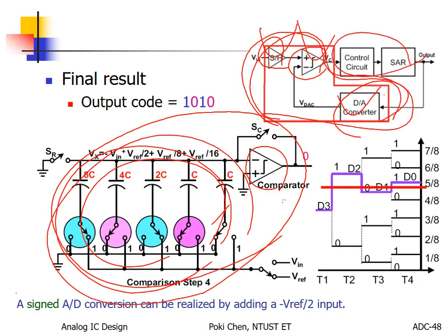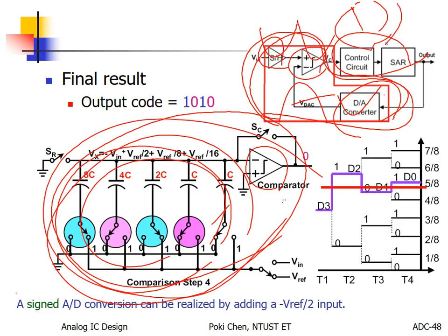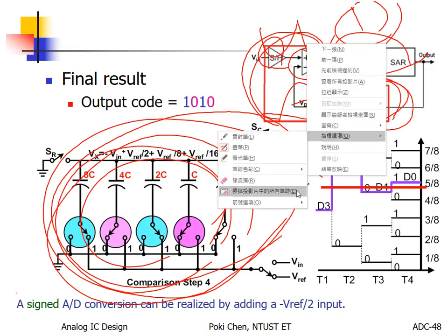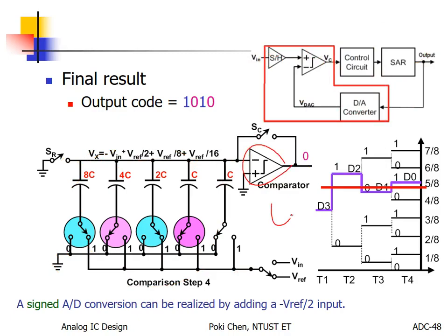Congratulations. For all the others, they are digital. This is analog. All analog part here, so you only need to apply cell-based design for your digital circuit. Please, for your future design, this is the best for you to start your new design. Reference to this. But you still need to pay attention: for accuracy, you need to design a good enough comparator with as small a VOS as possible.